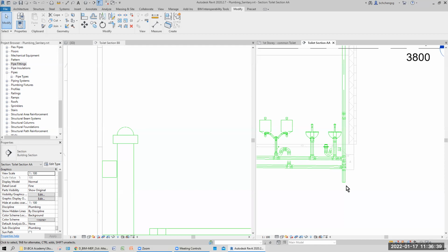You see? So for a lot of piping, let's say water transfer, the main supply piping, because it's pressure, the bigger the pipe, the pressure drops; the smaller the pipe, the pressure increases. So as an engineer, they need to calculate the pump size required to pump the water to the rest of the usage. Now, normally, let's say we talk about HDB. For the HDB incoming water supply, if we don't have extra pumps or boosters to push the water pressure up, they can supply up to 3 to 4 storeys.